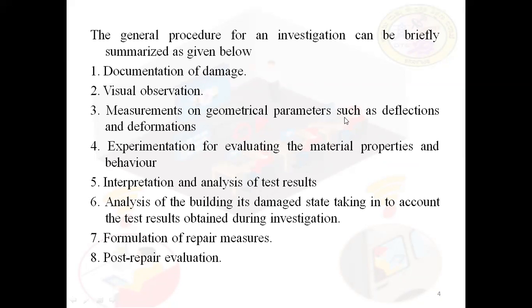Measurement of geometrical parameters such as deflection and deformations, experimentation for evaluating the material properties and behavior, interpretation and analysis of test results, analysis of the building and its damage state, taking into account the test results obtained during investigation, formulation of repair measures, post-repair evaluation. So these are some of the general procedure for an investigation.